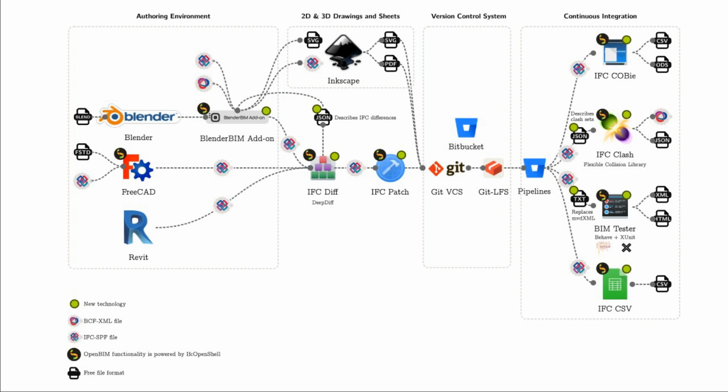And in this pipeline, certain IFCs had drawings automatically generated, export errors from proprietary vendors were automatically patched whenever there was a new upload. We used Git to track version changes, and COBie data was automatically extracted. Clashes were automatically checked, BIM exchange requirements were audited based on the execution plans and contracts, and various spreadsheets of particular data were extracted as well. And this is an example of the flexibility that these open utilities give you. You can use these utilities as complementary to your existing workflows.